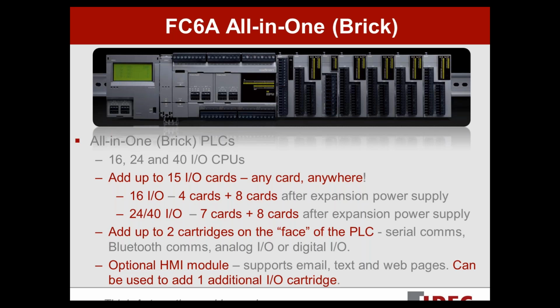Now, the 16 I/O PLC, which is the baby of the bunch, you can have up to 4 I/O cards. Then you need to add an expansion power supply that goes right onto the last I/O card. Basically, it snaps into that. Then after that expansion power supply, you can add 8 additional cards. So the 16 I/O will support a total of up to 12 cards. And again, that's with that expansion power supply.